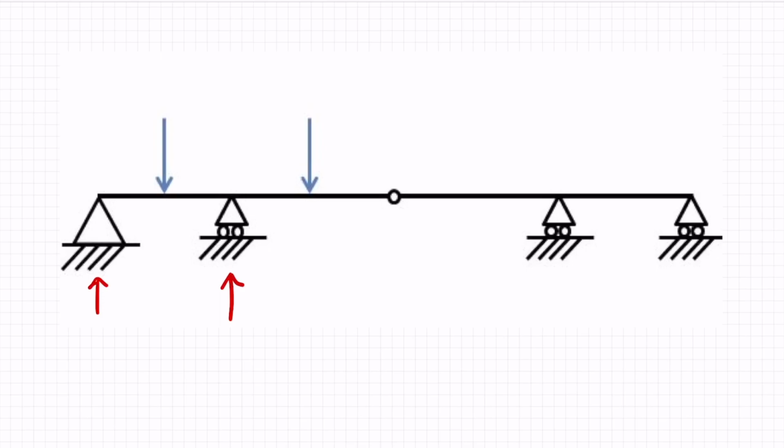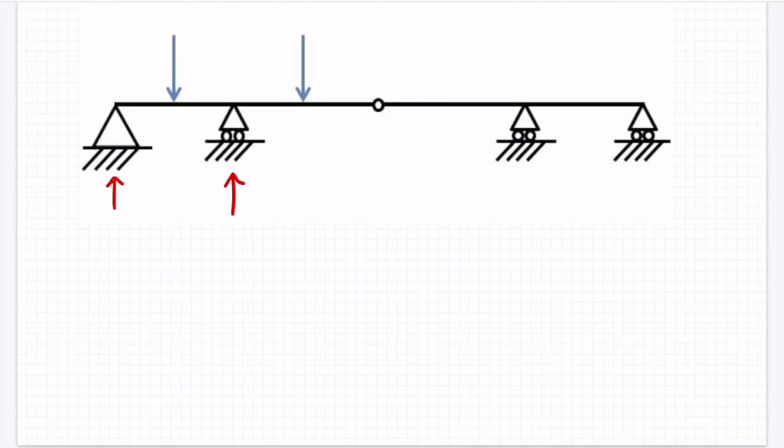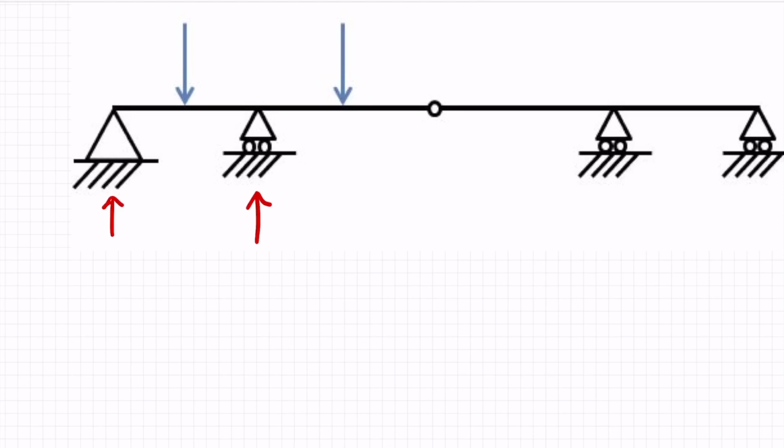But it's a bit more hazy once you get to the right hand side of that concentrated force. What I like to do, if I'm really unsure, is imagine if this were a mechanism, what would happen? What would be happening if this were a mechanism? Or if we just keep pushing it to slightly unrealistic deformations. So let's try and draw in a deformed shape. So I expect the beam to do that.